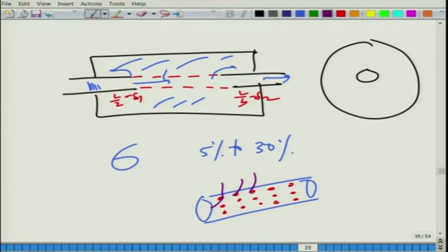So, basically not allowing the flow to expand freely, but at the same time allowing the waves to interact with the cavity, is what the perforate does, and it really kills, or does not bring into the picture, the separation noise. Experimental evidence has it that this is much better than just allowing the flow to expand. And in real life also, no one really uses a bare extended inlet and outlet chamber. People really need to use some perforated element, and that is why these perforated elements are studied a lot. And in all commercial vehicles, I will show you a couple of photographs, they are there.